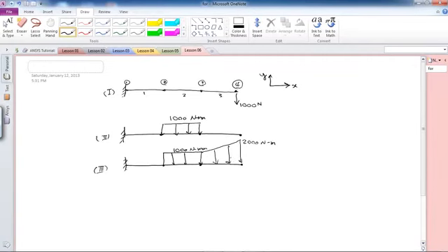What you will learn in this lesson is how to modify your loading per analysis without needing to redefine your model, reselect your elements, and reapply the cross-section areas or real constant and materials. All you want to do probably is just change your loading conditions. So you will learn how to do this in this example. Plus, the other thing I want to teach is how to read nodal results.